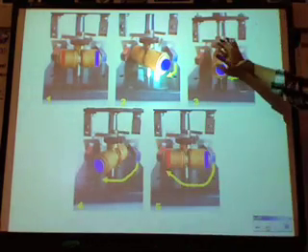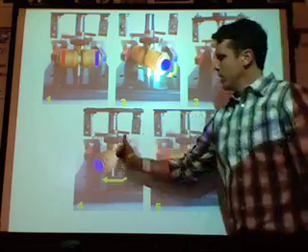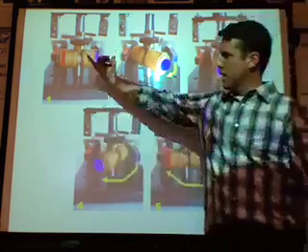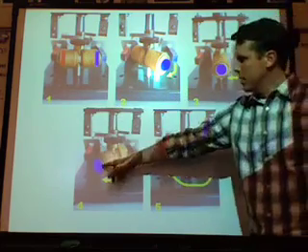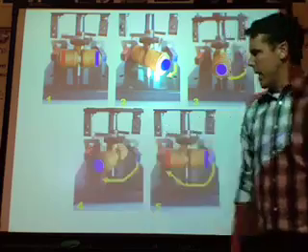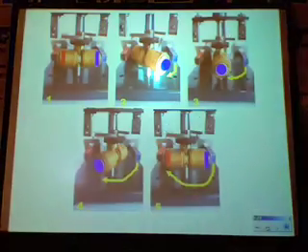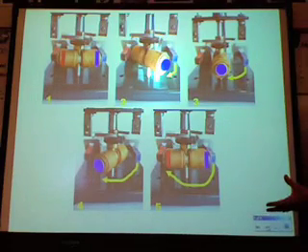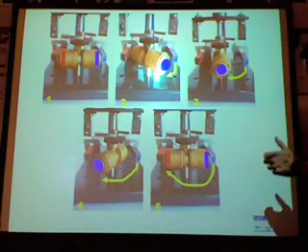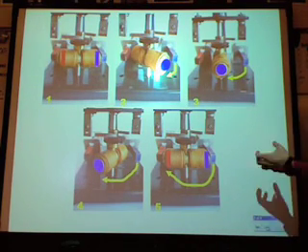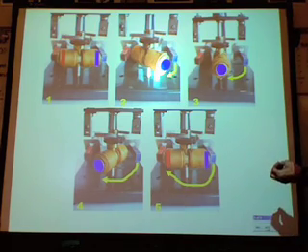Now, if it wasn't for our special connections up here on this collar, our coil would only turn halfway around. It would start here and turn halfway around. Once we got to this point, the blue and the red would be attracted, and the red and the blue would be attracted, and the coil would stop moving. It would freeze up, which is exactly what you saw on the motor I made, the swing motor. When I held down the switch, the coil just sticks to it. It no longer swings back and forth.